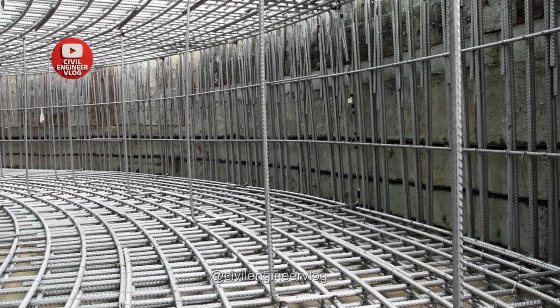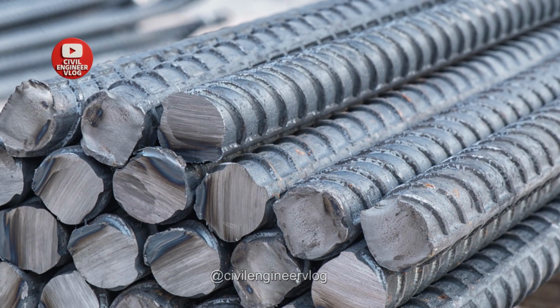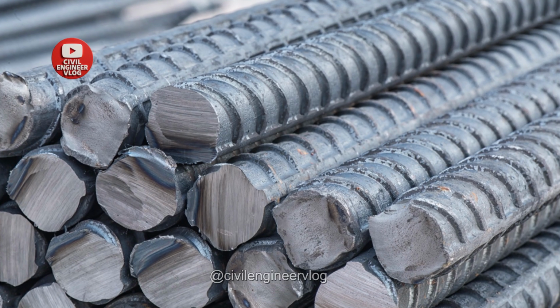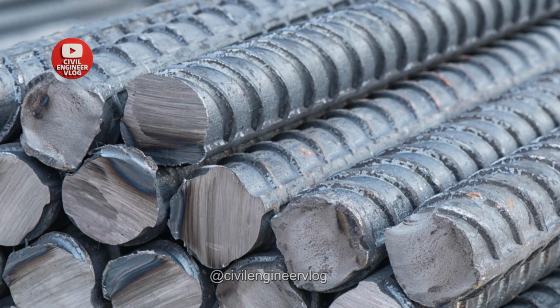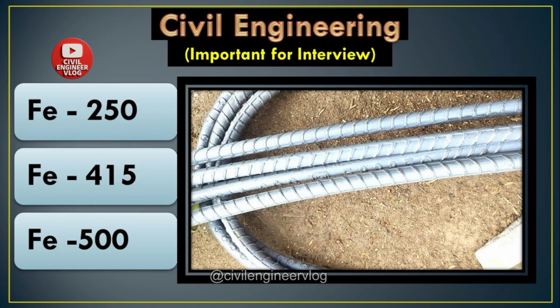Not checking the quality of rebar. A major mistake many people make is buying rebar just based on price, not quality. But remember, weak rebar equals a weak structure. Every rebar has a grade like Fe 415, Fe 500, Fe 550. The higher the grade, the stronger the steel.